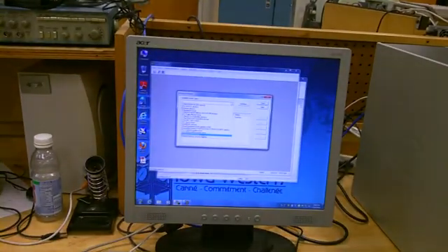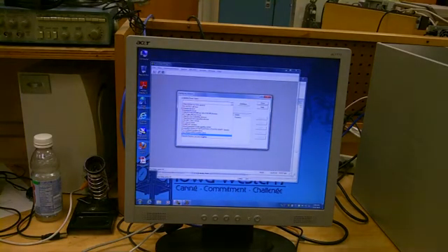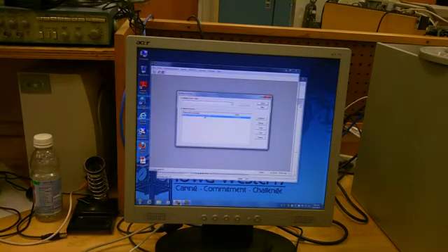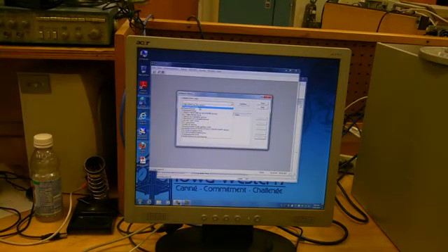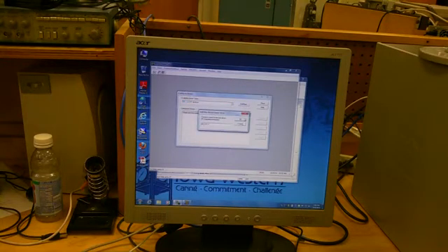So anyway, right now the driver that's there is the wrong one, so we've got to get rid of it. Click on the driver that's running. Click on that guy. Hit stop, and then hit delete. All right, so we got rid of the driver we don't want. We want the driver that talks to the RS-232 port. So RS-232 DF1 devices is the driver we want, because we're coming through the RS-232 port, and we clicked Add.